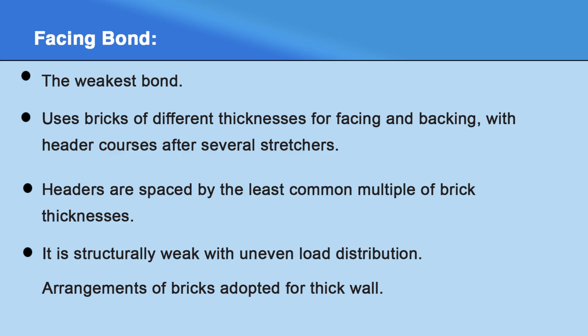The facing bond is typically used for aesthetic purposes where the exterior appearance is prioritized over the structural integrity, making it unsuitable for load bearing walls or applications where strength is crucial.